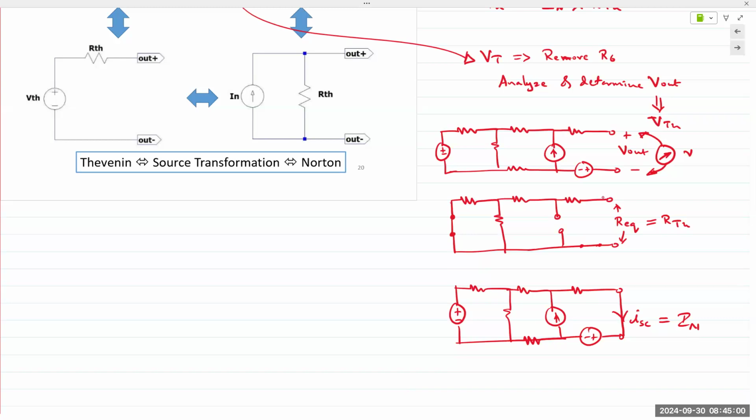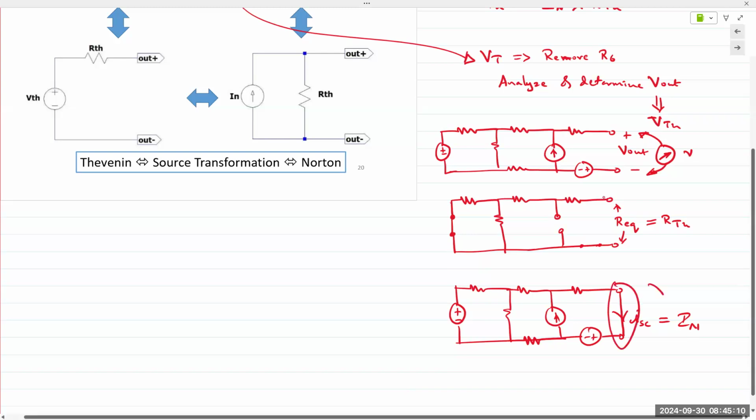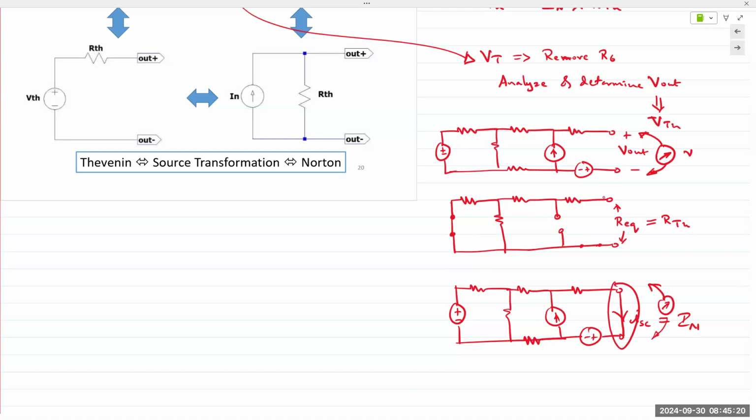You don't do anything. You simply change the mode and the physical terminal on the meter, change it to current. A multimeter in ammeter current measurement mode is a short circuit. So you don't need to short the circuit. Remember, we need a short circuit. If we have a meter in current measurement mode, it's going to provide the short circuit as well as measure the current itself. Now, that's why I said actual real life measurement does not take more than 2 minutes.